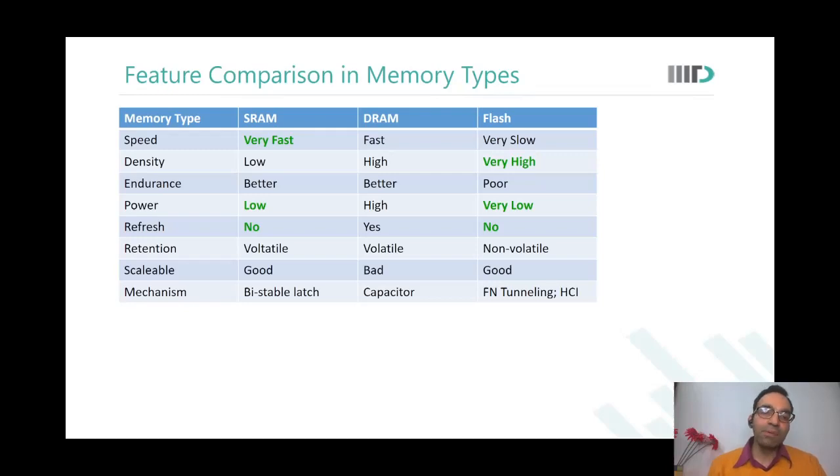Okay. So what happens in such systems is that there is some non-volatile memory also placed on the chip. The power down sequence involves storing the present state of the processor onto that non-volatile memory, and the boot up operation involves recovering that information from the non-volatile memory and booting the system up in the desired manner. Okay, so whenever the power is on, this booting will load the instructions into volatile memory. Yes.